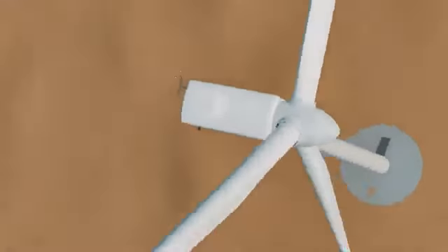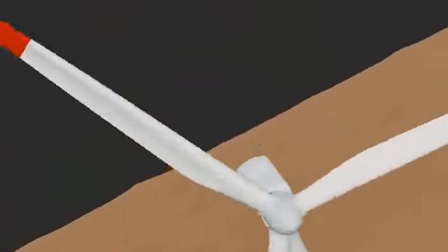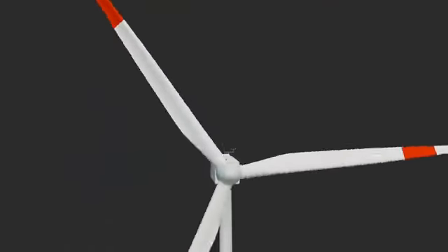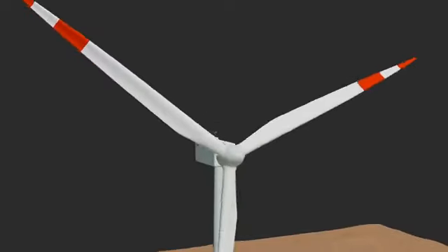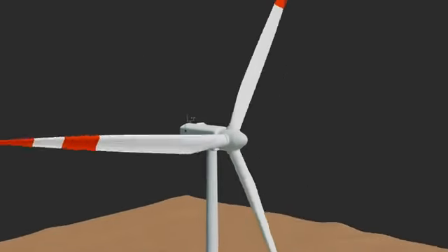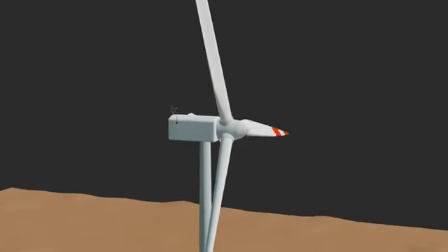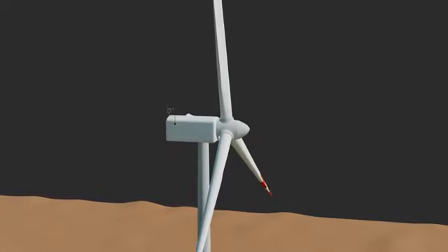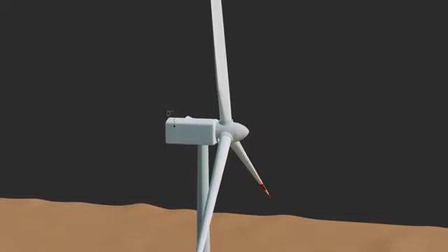To generate the 50 Hz electricity required by the electrical grid, the generator must rotate within a limited speed range, approximately 1400 to 1600 RPM for a typical 4-pole generator. However, wind speed constantly varies. A pitching mechanism is used to rotate the blades around their longitudinal axis, allowing them to capture more or less energy and maintain optimal rotor speed.